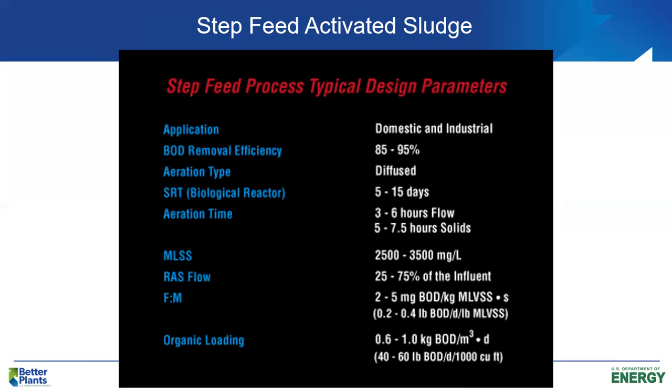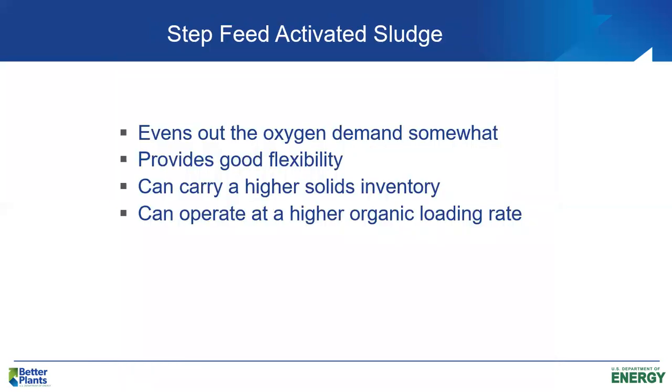Normally, SRT will be about 5 to 15 days. We'll have about a 4, 5, 6 hour hydraulic detention time. Around 3,000 milligrams per liter mixed liquor suspended solids, F/M ratio 0.2 to 0.4, and we can operate at a slightly higher organic loading, 40 to 60 pounds of BOD per day per 1,000 cubic feet. As I said before, it evens out the oxygen demand somewhat by distributing it along the length of the reactor. And again, it's a very flexible process.